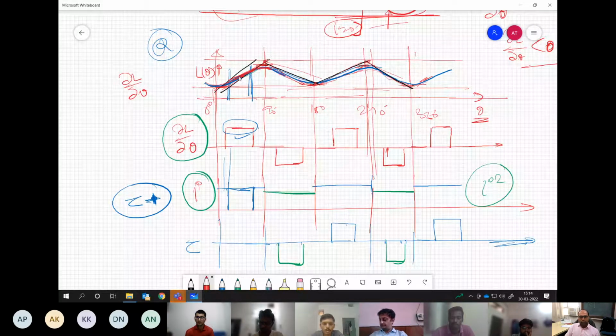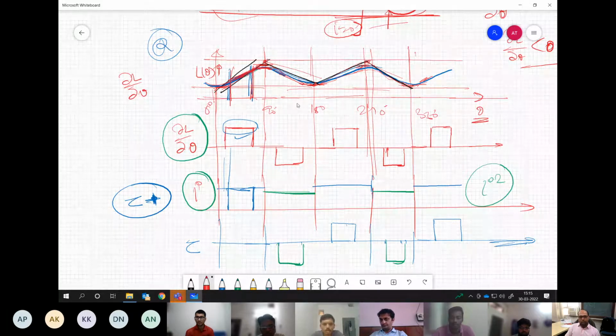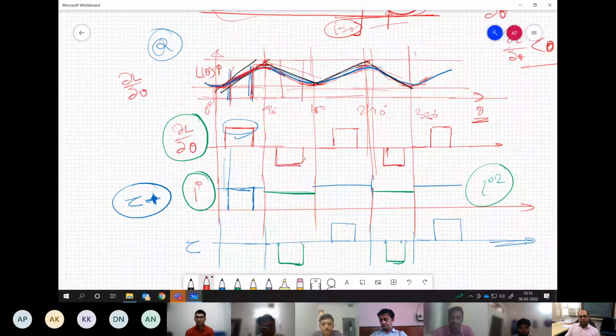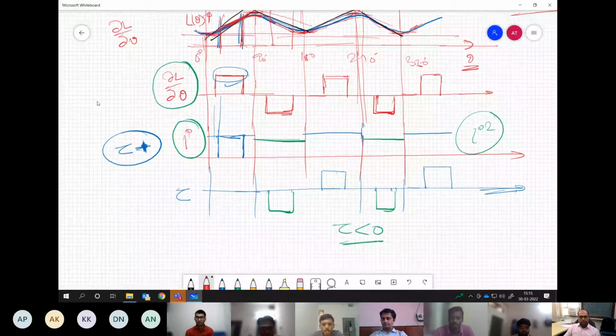So effectively we have a zone where inductance is varying almost linearly. So dou L by dou theta is clearly a positive, non-zero DC value, you can say. Then for the next segment, this will be a non-zero negative DC value, and so on. It will keep alternating dou L by dou theta. Now, if you keep a constant excitation, let's say this blue current we have drawn, if this is extended continuously throughout the rotation, what we will have?